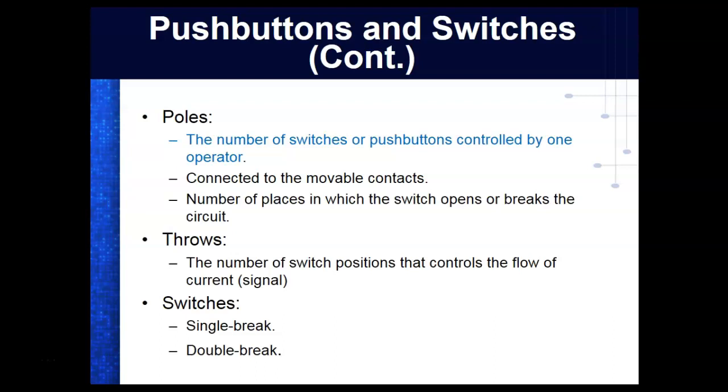Now in industry, we have what we call double break and single break, and I don't know if they show that, but on a single break, what we would do is we would come over here, and it would technically look like this, even when it's wired. On a double break, we'd have a contact on this side, a contact on that side, and then the operator actually comes over and does this. And this right here will be on a spring. So if it's momentary contact, it'd be on the spring.